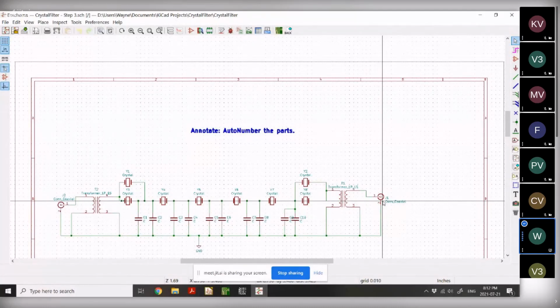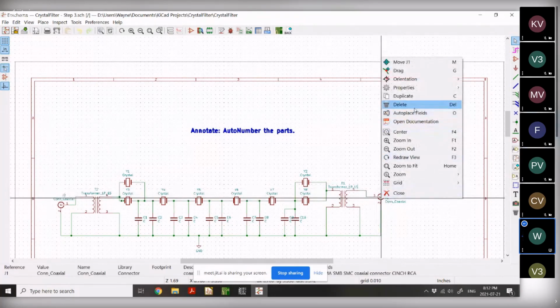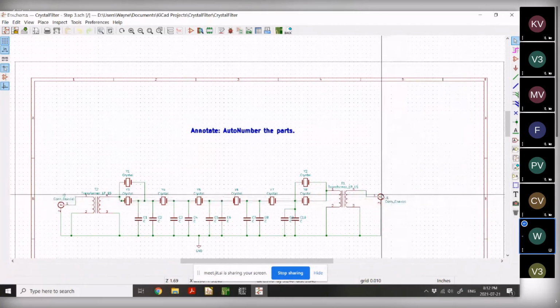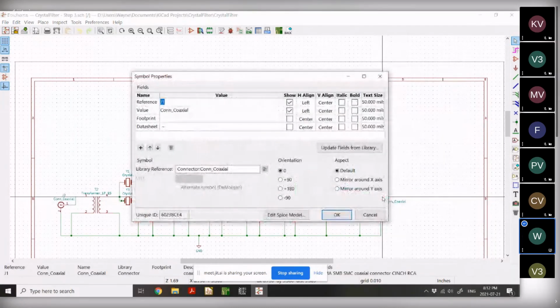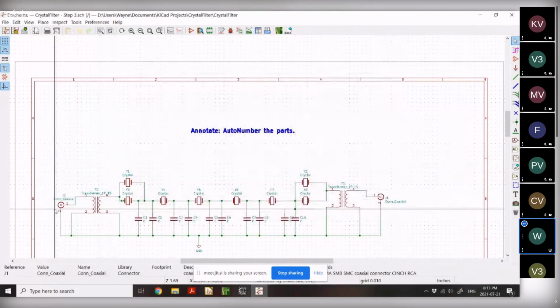But I could imagine that if you're drawing an amplifier, it might be kind of important that your input is named correctly. KiCad allows you to go in here and directly edit it. It doesn't show me the keys, so just hit the E key. You can change the reference to J2, then change J2 to J1. In LTspice, because it's directly connected to the Spice model, it prohibits you from making that kind of change, because all names must be unique in the LTspice model.